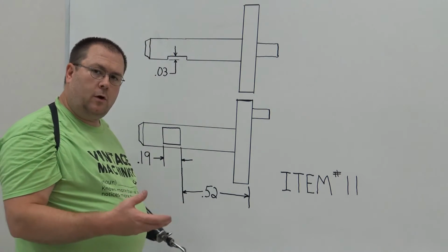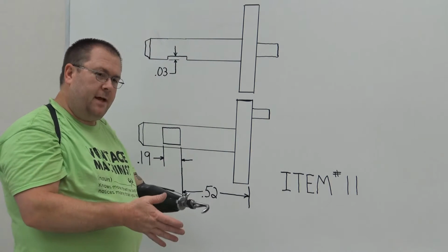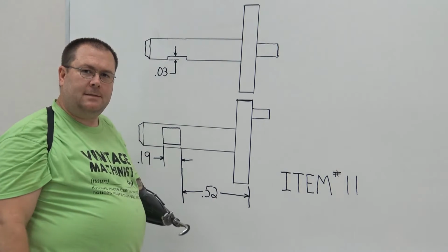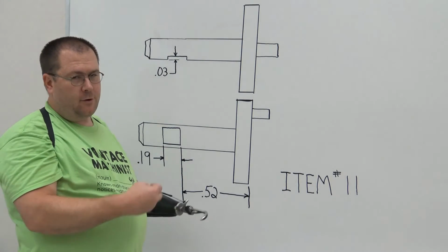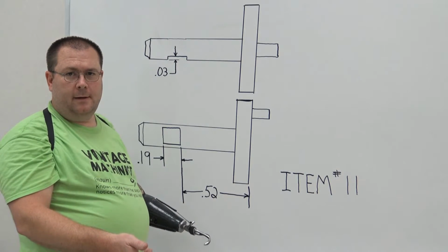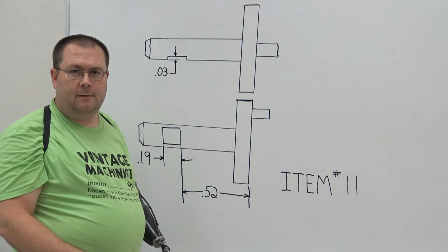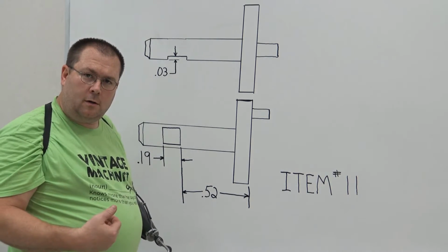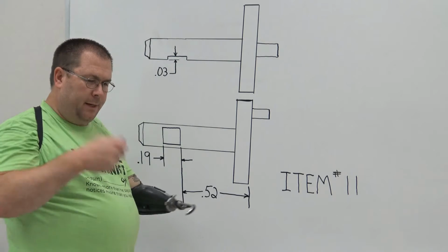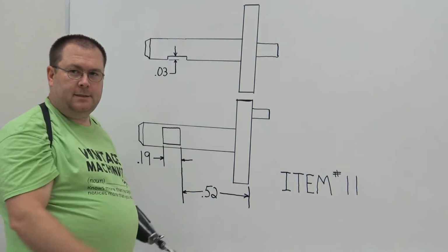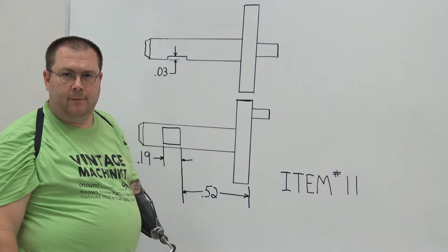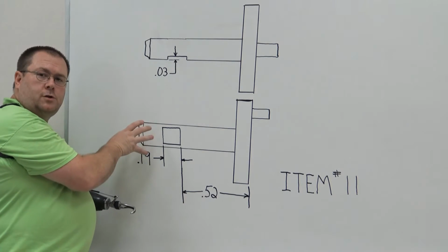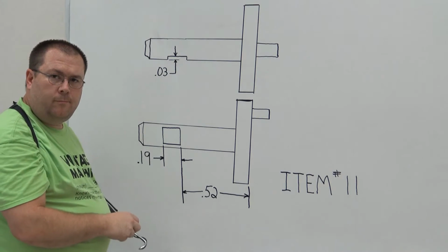If I hold on to it and push the vise, putting pressure on the two tangent sides, I'm going to put flats on it. Well, now if I have a crankshaft that's got flats on it, it's not going to run real well, right? You wouldn't take your small block Chevy engine out of your car, take the crankshaft out, and beat it with a hammer and put it back in and expect that it's going to run the same. We're not going to do the same thing with this. So we're going to hold on to it with a precision tool.